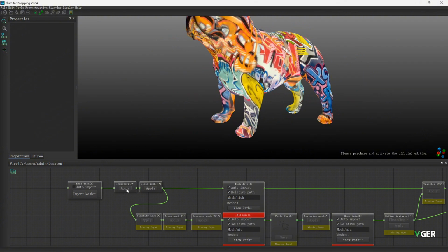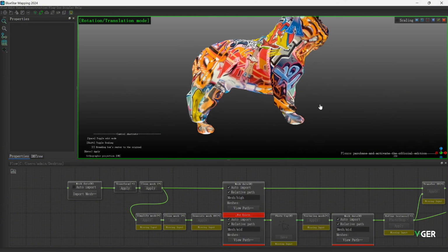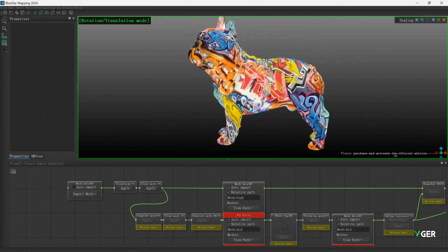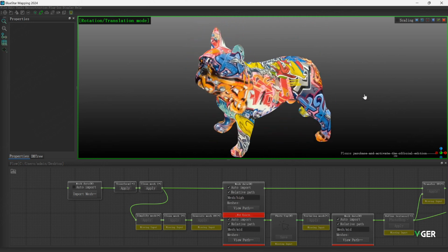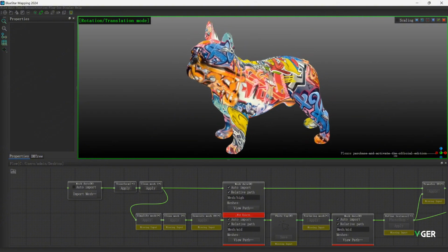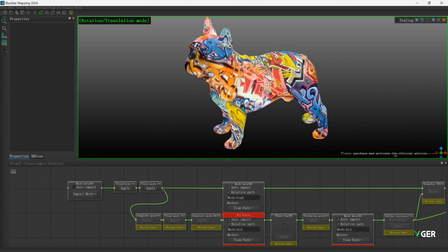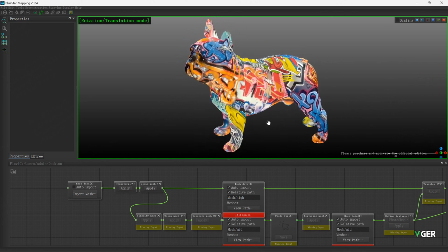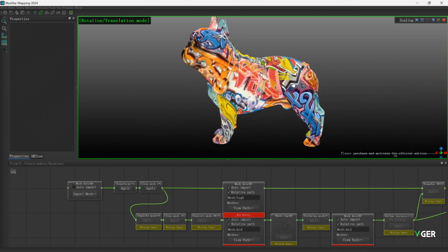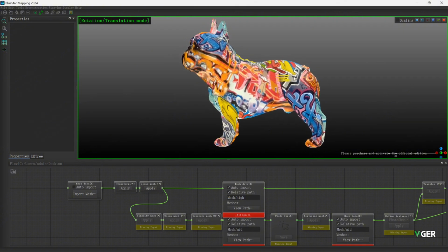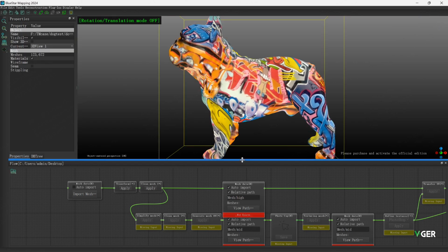Now, the second thing is to do a transform. This helps to quickly align the data. You can use the left mouse button to rotate and both mouse buttons together to pan the object. Simply put it in an upright position in the middle of the window. Should be okay. Click on the check, apply. All right, that's the second step.